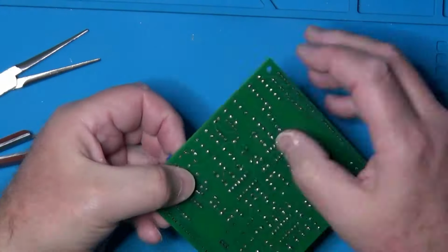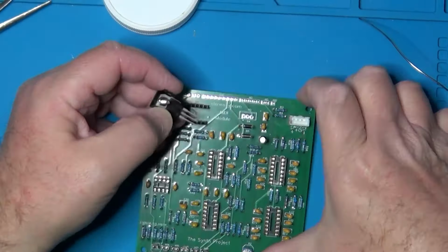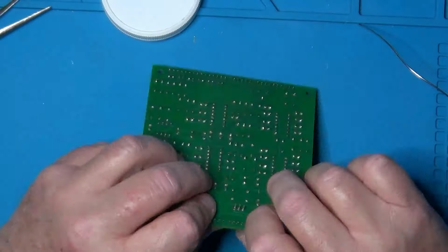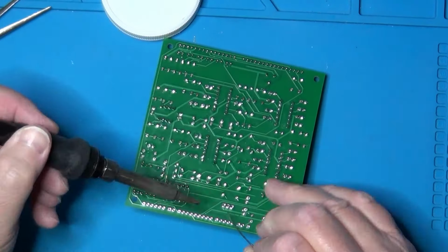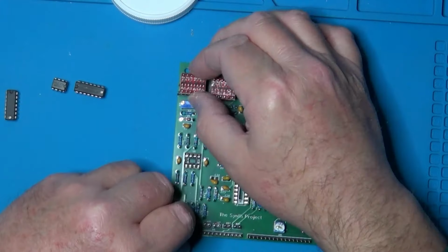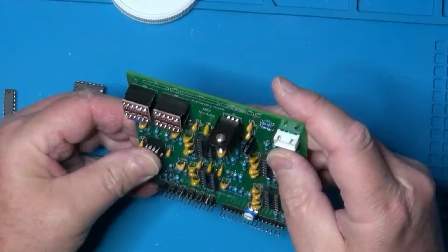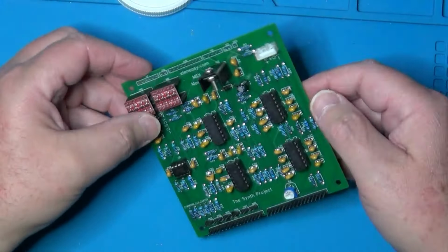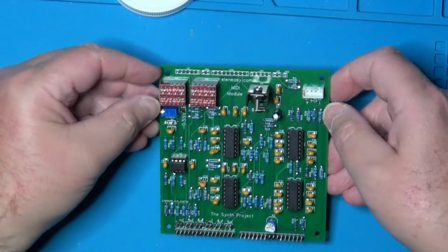Semiconductors were the last I soldered to the board, as I usually prefer to do. In fact, I even kept for last the 9V regulator, which I soldered after fixing a heatsink on it. Finally, I added all the components that needed to be inserted into sockets, the level adapters and the integrated circuits. And this is the complete board. Well, almost. There was still a whole row of pin headers missing.